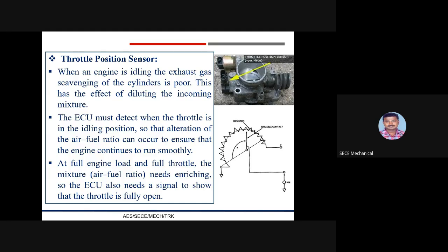Some engine control units, ECUs, or electronic control units also control the throttle position, called electronic throttle control or drive-by-wire system. If that is done, the position sensor is used in a feedback loop to enable that control. Related to the TPS is the accelerator pedal sensor, which often includes a wide open throttle, that is WOT, sensor, used in electronic throttle or drive-by-wire systems. The modern sensors are non-contact type. These modern non-contact TPS include Hall effect sensors, inductive sensors, magnetoresistive, and other sensors.